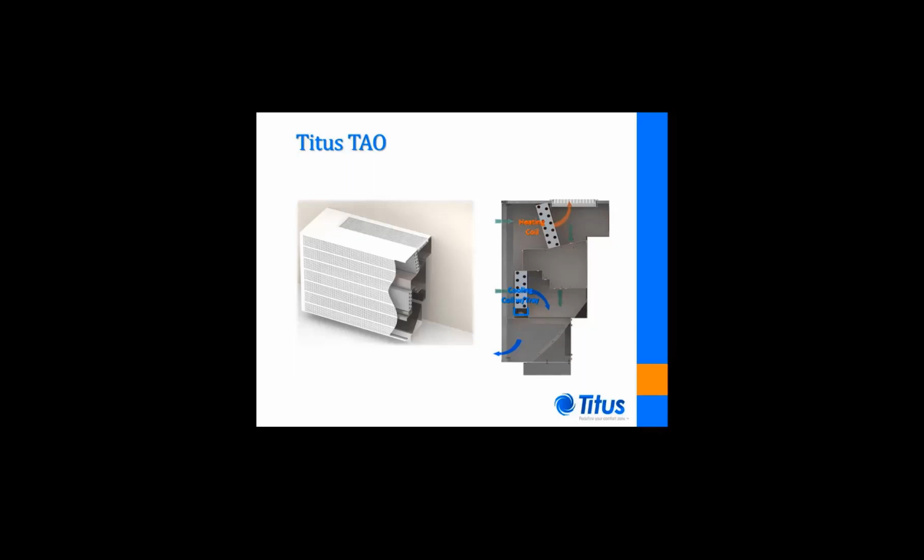As the cooling coil is vertical, a condensate tray is provided to catch any moisture that might form during periods when the room dew point exceeds the supply water temperature. The unit also consists of a ducted primary air plenum, several rows of nozzles which inject the plenum air into two separate induction sections, and separate mixing sections where induced air, room air, mixes with the primary air injected by the nozzles before being discharged to the classroom.